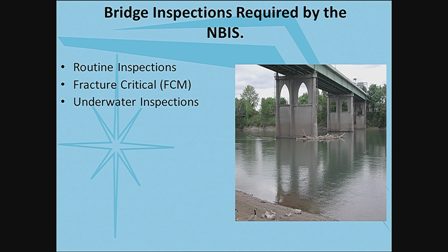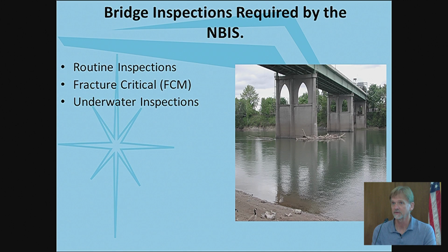Then there's the underwater inspection reports. Those are obviously the below water condition of the substructure of the bridge. And ODOT has their own dive team. And they also look at your bridges, the local agency bridges, the state bridges, other state agency bridges. And so those are done on a maximum of 60 months. Some are on 12 months, depending on the condition of the substructure or the scour conditions.